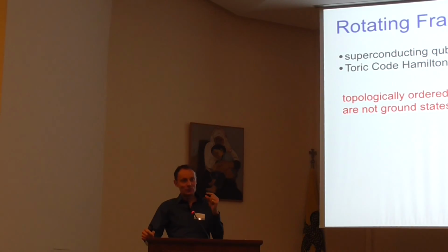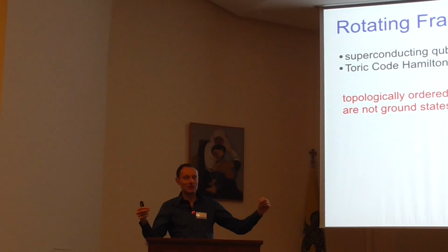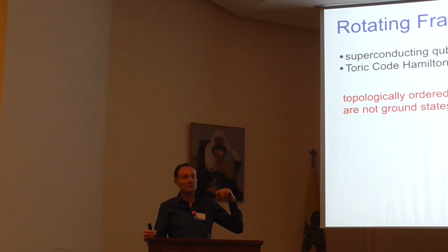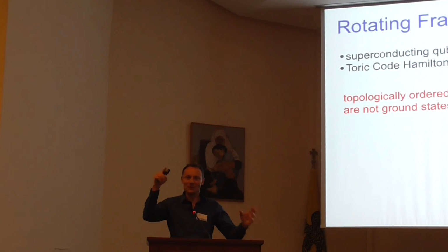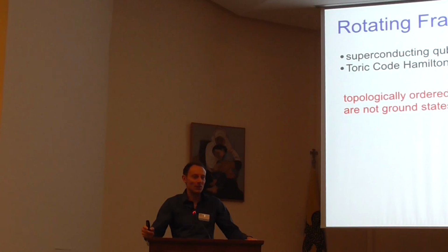If I would choose a smaller inductance because I have a galvanic connection between the qubit and this grid, this would generate a very strong coupling between those. And I'm afraid that the two-level approximation for the qubit would break down. Suggesting junction arrays is a pure matter of size. Anton, you have estimated this at some point: if I would do this in coils, the inductance would eat up half the chip or so.